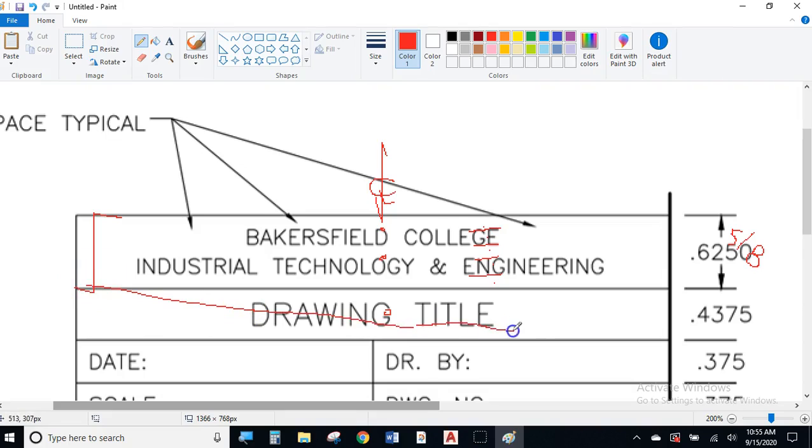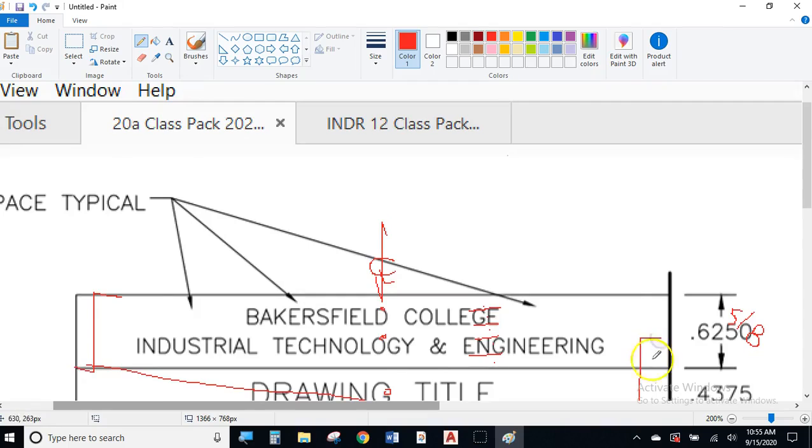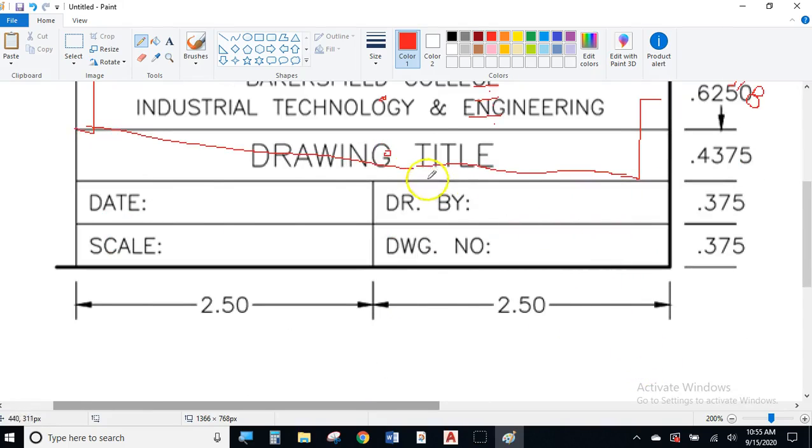Just a straight line, corner to corner. Ignore my poor Microsoft Paint drawing skills. And on the line, you'll have a midpoint, right? Well, snap the middle center of the justification on the text to the midpoint on the line. And that'll keep it centered top to bottom and centered left to right.